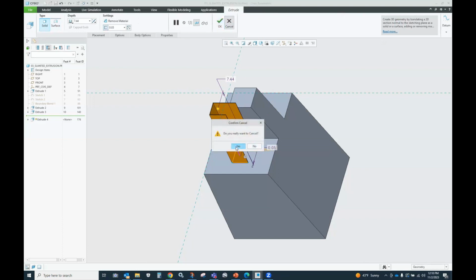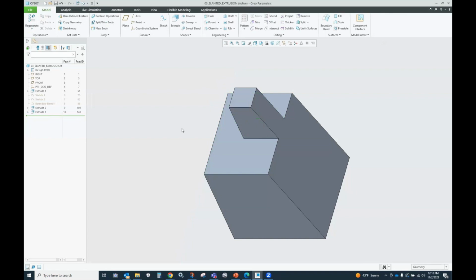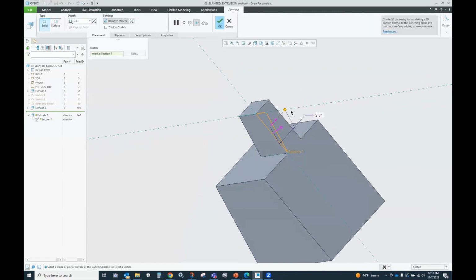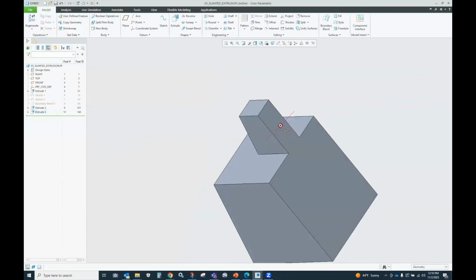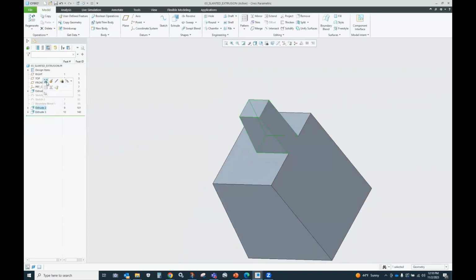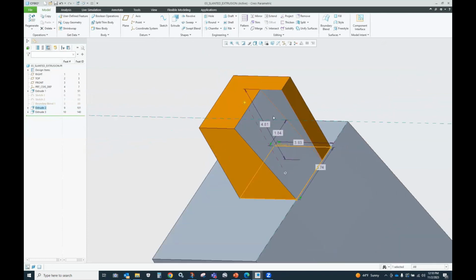So I need to understand really how Creo manages and uses these open cross sections. First of all, the one thing I did wrong with this was my depth option there. That's bogus, right? It worked here, but what happens if I edit this extrusion and I do something like that, now my feature doesn't go all the way through, right?